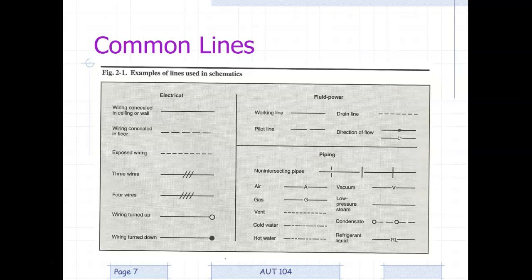But anytime you have lines that are actually physically connected, not laying over each other, but they are making a physical connection, like you come to a T or you come to a four-way path, it will have a dot to show connection. No dot, no connection. Okay? Clear up that confusion now, because believe me, that happens a lot more often than you'd think.